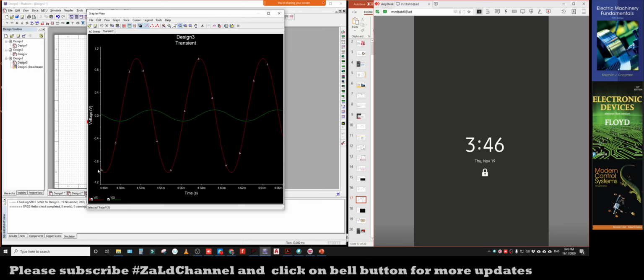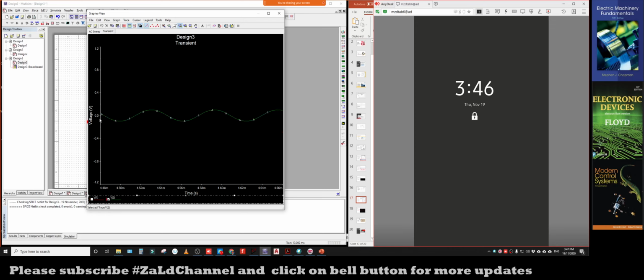So meaning that we input the signal at 1 magnitude, and we get the output at 0.1 magnitude, which is 10 times smaller. This green signal is 10 times smaller than the red signal, which is input. So this is the input signal, this is the output signal, the smaller one. So we wanted to confirm that this 16 kilohertz corresponds to negative 20 decibel, which is an output signal 10 times smaller compared to the input signal.